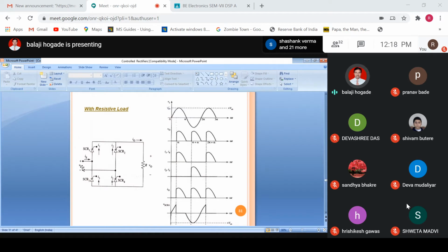Please remember, this is an AC source. Why is plus minus shown? It is assumed that it is a positive half cycle. So on the input side, you can connect these 2 terminals, draw a circle in between, and show an AC sign, the sinusoidal waveform symbol, that will also work instead of showing plus minus. Those who understand will know it is an AC supply, but someone may assume it is shown as a DC source, which would be wrong. So instead, you can draw a circle between these two and show an AC sign. That will be a better option. So on the input, there is AC.